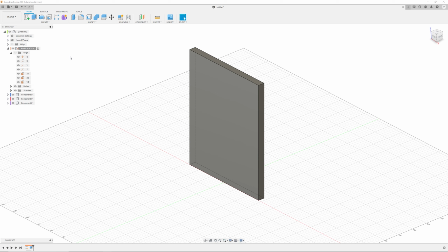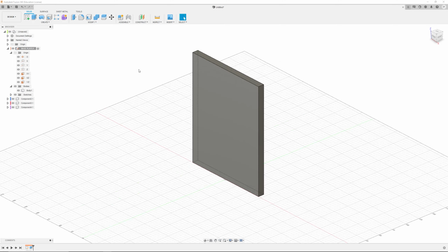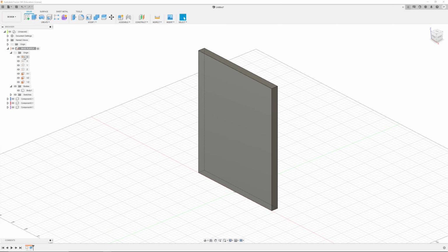However, from this point going forward in this class, everything that you will be doing from now on will be in this sort of methodology, which is every single component should only have one body inside of it. Every time you have a separate body, that separate body should be a completely different component. So the rules are changing a little bit, and the reason for that is to help your learning with the basics. And so now I'm introducing the proper way of assembling components in which you should only have a single body per component.